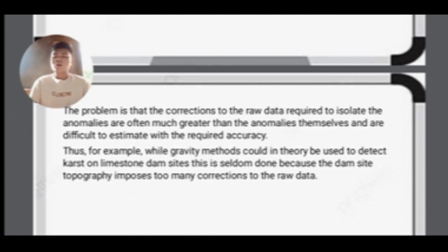So in theory, quite small cavities at depth will give anomalies detectable by modern gravimeters. According to the study of Greenfield 1979, the method is useful on limestone coastal platforms, which could be the sites for airports or similar construction which must be built on level ground.